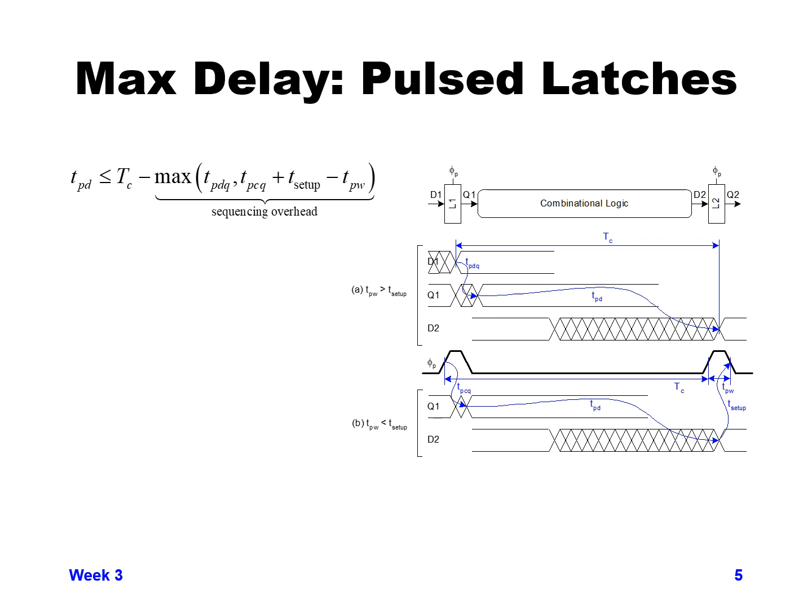So our starting propagation delay is T sub P CQ, clock to Q. And after Q1 is stable, then the combinational logic starts switching, and we have the propagation delay T sub PD through the combinational logic until we get to D2.